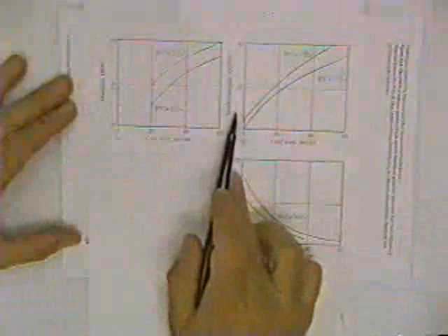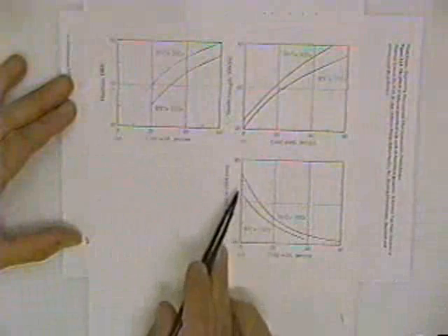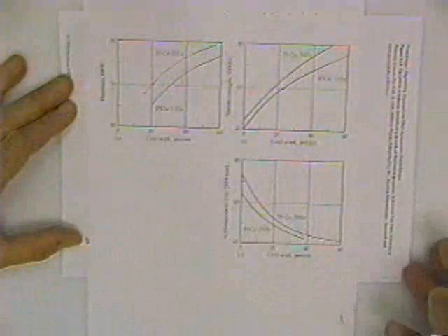And if you look on page 24 for the copper zinc system, you can see the change in hardness and tensile strength as you cold work the material, and correspondingly the decrease in elongation.